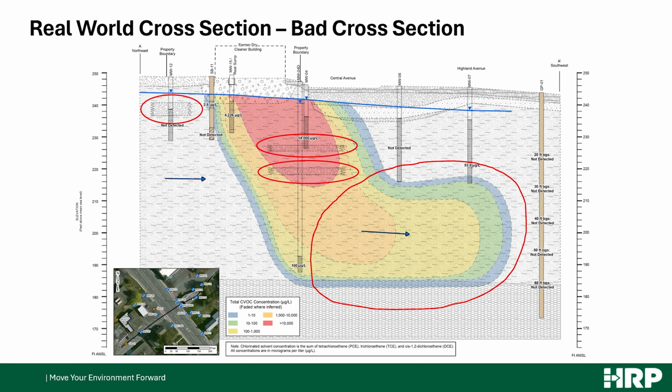This is also a good example of a very common problem that we see a lot in completed investigations, where the investigation is completely focused on what the concentrations of the contaminants are and where they are, versus looking at it from a geology perspective and understanding what the subsurface is like and how that impacts contaminant transport. Because you can see what they did here is they have detections, and then they forced the subsurface to sort of match where those detections are.